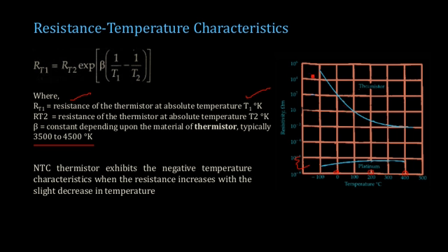but you can see that for a thermistor, resistance varies in the range of almost 10 raised to 5 to 10 raised to minus 2. So within that small change in temperature, your resistance is varying drastically, in a large manner. That is one of the main characteristics of a negative temperature coefficient thermistor, where it is highly sensitive to changes in temperature, and you have large variations of resistance available.